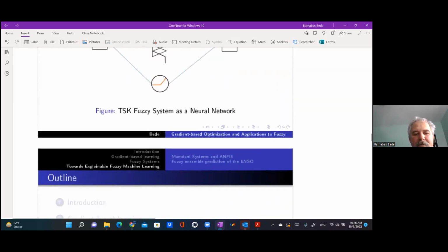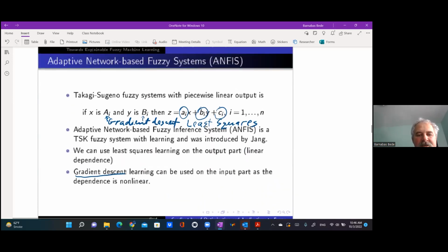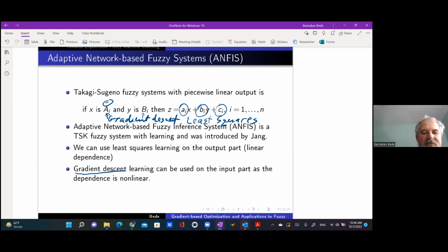Now, imagine this one here. Let's go back to this rule base. Input and output are fuzzy, so those will be easy to interpret. If you consider the most typical tipping in a restaurant problem in fuzzy logic, that would be basically: if food quality is high and service is excellent, then tip is generous. So imagine here, this Takagi-Sugeno rule would be: if food quality is high and service is excellent, then tip is 3x plus 4y plus 15, or who knows what, some values there.